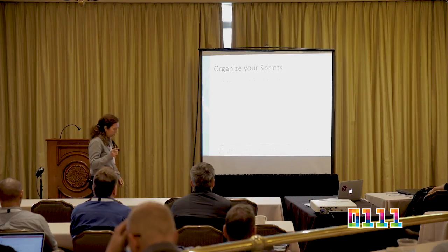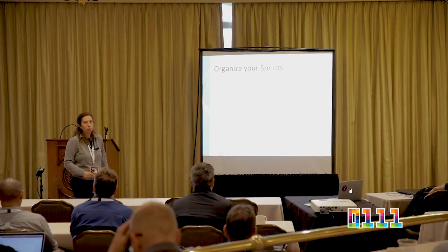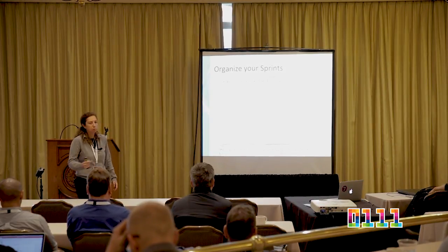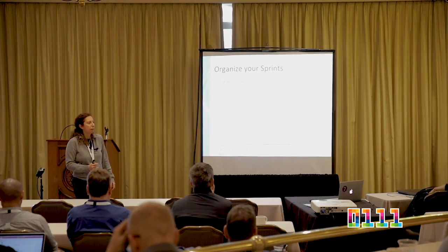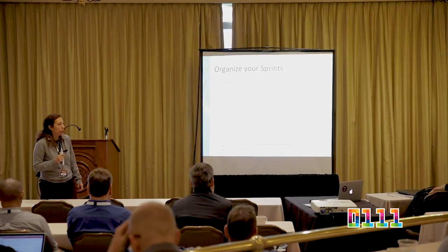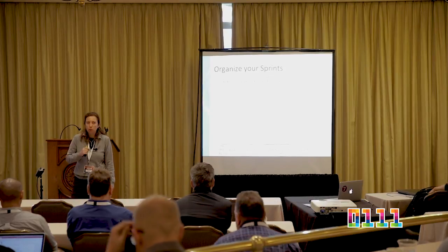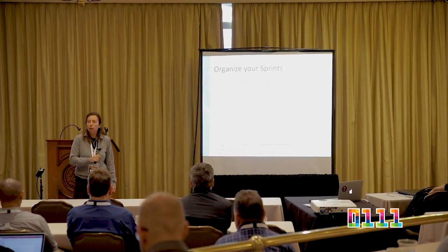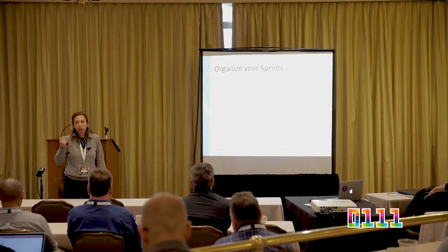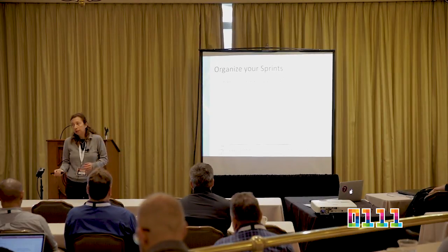But one of the things that I didn't talk about is how do you reduce the risk when you're talking about compliance testing? How do you not fail your EMC testing or EMI testing? Just like any other tool set that you would purchase to have in-house in your lab, those should be part of the tools that you have in your lab. So you run those tests in a continuous fashion. You make a change, you build your prototype, you test it.